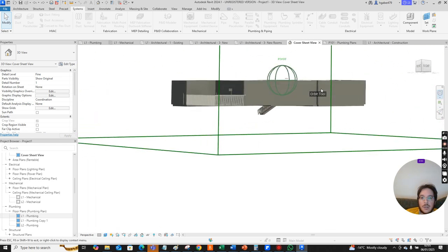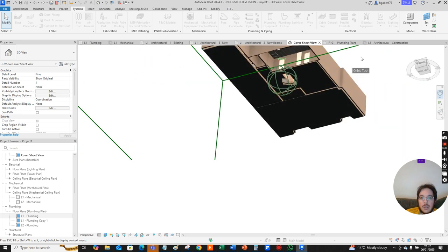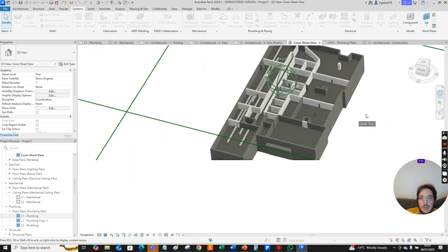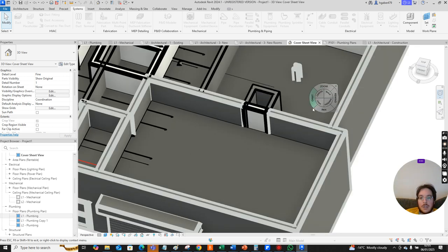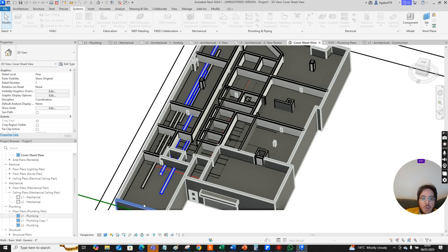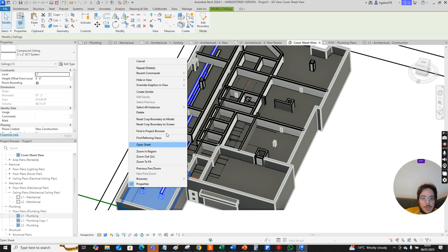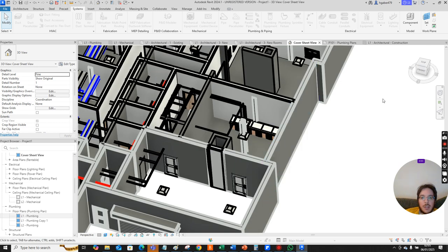So look, if we got our building here, I had a kitchen, but I couldn't see the kitchen now because we've got a ceiling. So see if we can get rid of the ceiling. We're gonna go hide categories. We're gonna hide the ceilings. So this is my building,